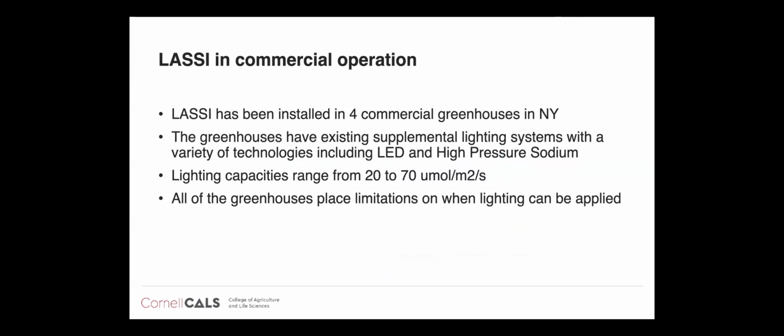Okay, so this was some data where we were demonstrating LASSI in some commercial operations in New York State. We have them in 4 commercial greenhouses with varying levels of technology. A couple of them have shades, a couple of them don't. One of them has high pressure sodium and the rest are LEDs. The lighting capacities are pretty low, from 20 micromoles per meter squared to 70.